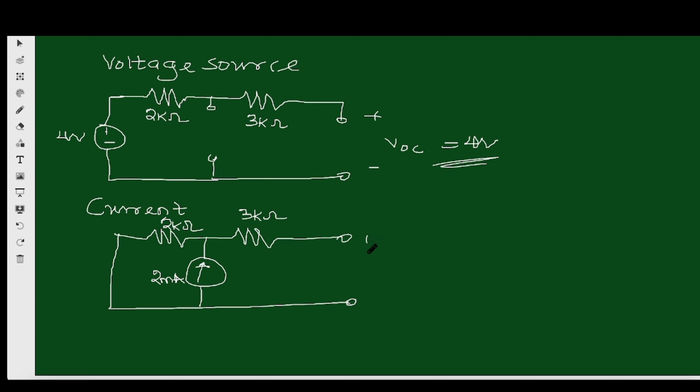But right now, to get our V prime, what do we have? The voltage that is on this combination. How do I get the voltage on the combination? This is the resistor, this is the current. It's a single loop because nothing is coming here. Any current that is coming here is just going through this single loop. So what does that mean? We have IR, which is 2 milliamperes multiplied by 2 kilo ohms. So V prime is 4 volts.